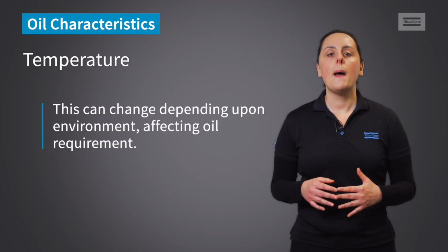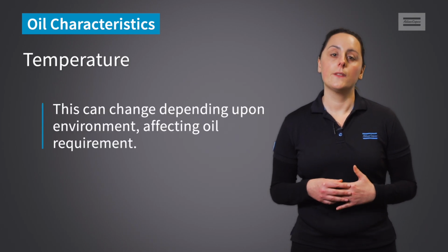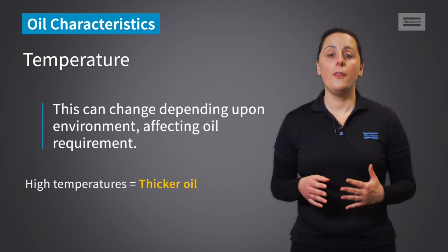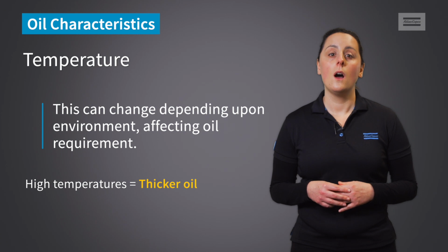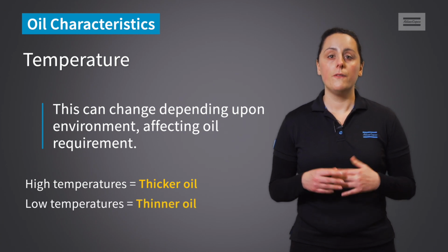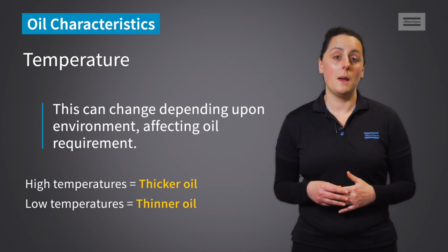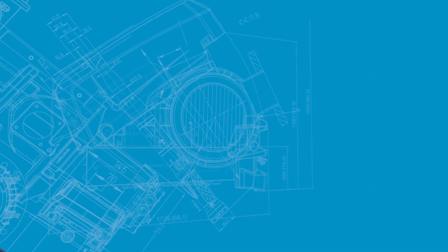Temperature can change depending upon the environment, affecting the requirement. In extremely high temperatures, a thicker oil may be required, ISO 68 perhaps. Conversely, in extremely low temperatures, a thinner oil may be required, for example ISO 22.